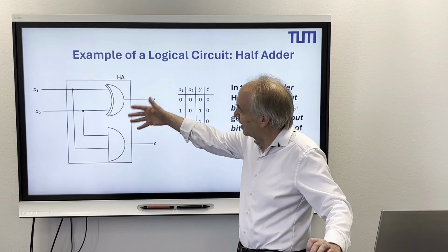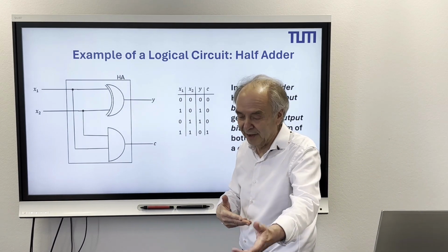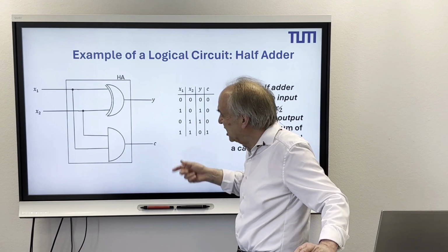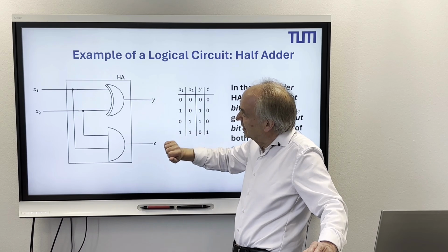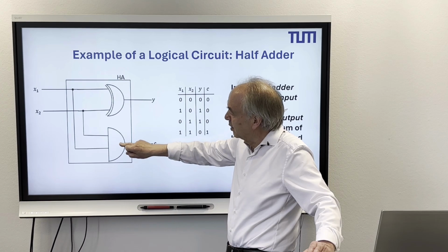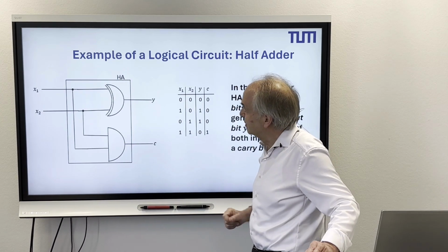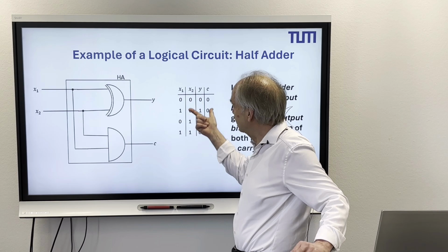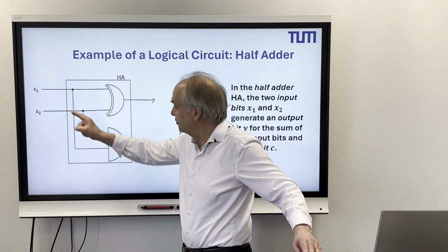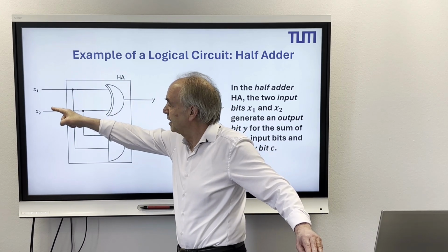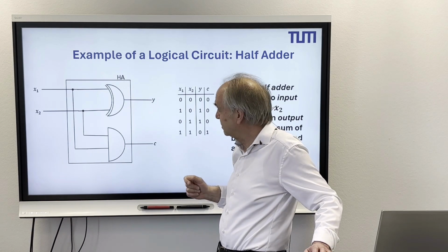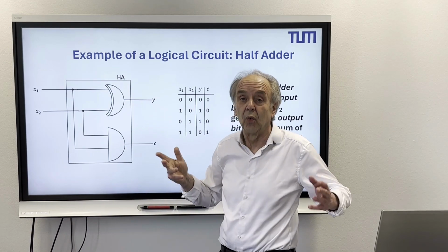And that is realized here. Leibniz realized it in a mechanical way with gears and so on. But here, in an electronic way, we combine the exclusive OR gate with the AND gate. And it is very easy to understand; here is the corresponding truth table. And here, if you consider the two inputs, 1 and 1, then following the exclusive OR gate, we get 0. Why?